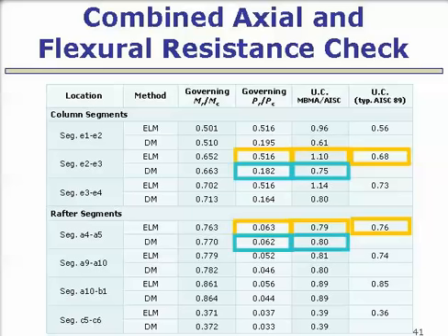In a typical design calculation working off of the prior AISC 1989, we get 0.68. That was with a typical approach of saying, oh, K is 1.5, and we keep moving along. Doesn't matter how many leaning columns you put in there, K is 1.5.